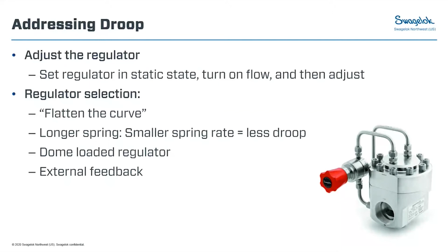What sort of filtration would you recommend when installing a regulator? Yeah, another really good question. This is another scenario where I hate to use the term always, but for the most part, I'm always going to recommend using filtration with the regulator. There are soft sealing materials in the regulator, and they can be damaged. And I think lack of filtration is one of the number one reasons that we see regulators coming back or not operating properly in the field.